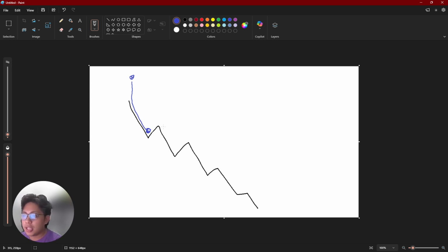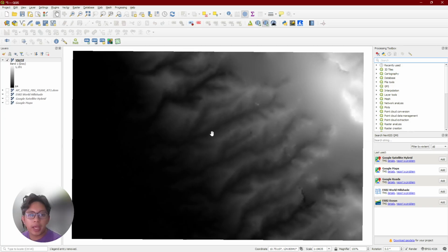So you'll notice that when you run your delineation, it's sometimes incomplete. It's not connected. What fill DEM does is it connects these dots. It connects the line by filling these gaps. So now, when you pour water here, it will be continuous. So you have connected river channels. Let's go back here on our DEM.